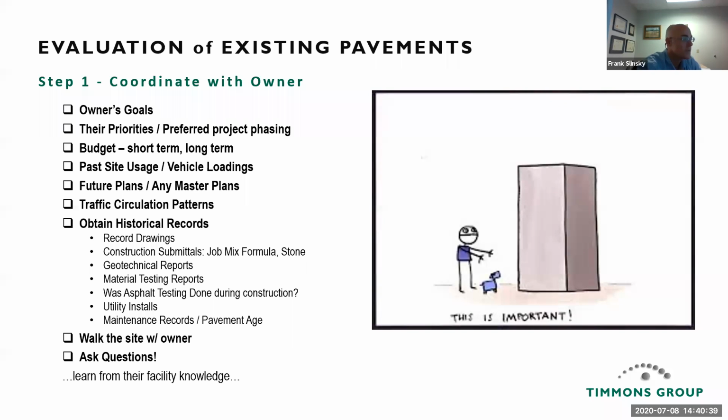Was any asphalt testing done at all during construction? Utility installs, find out where your utilities are, your constraints, possible depths. And to just obtain any maintenance records. This is all the information to build a background for this evaluation. And walk the site with the owner, very important. Ask questions, learn from their facility knowledge.